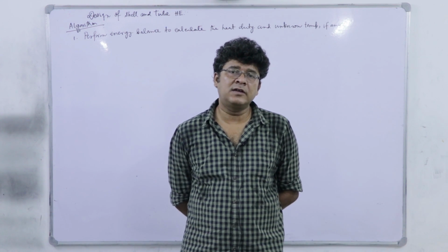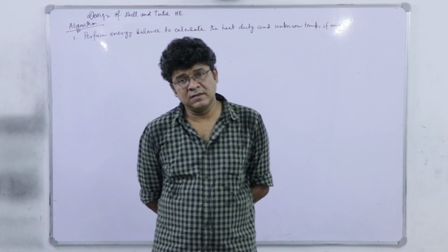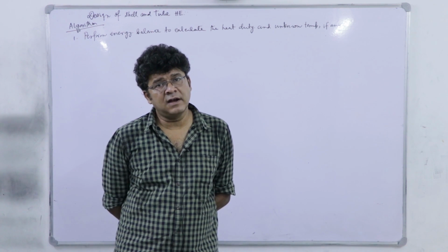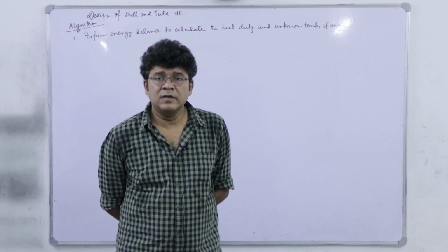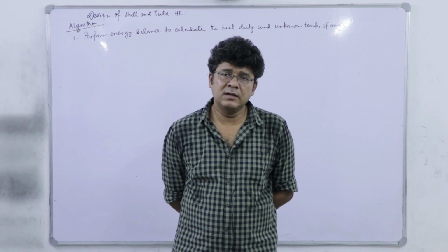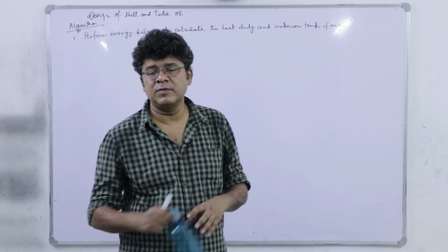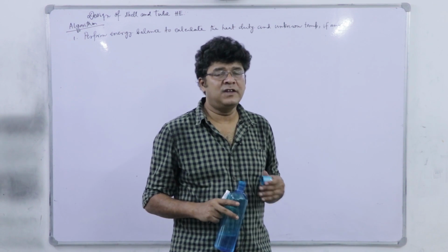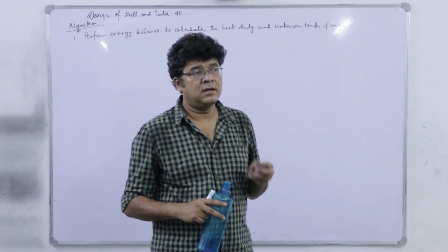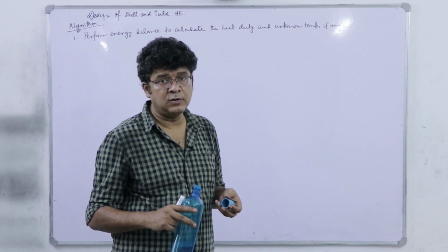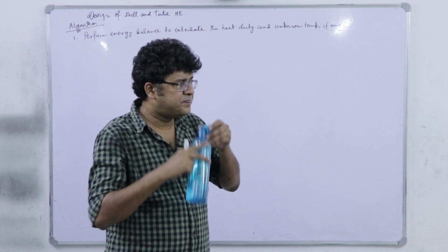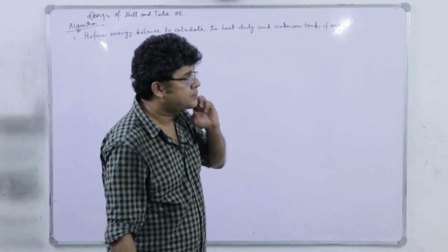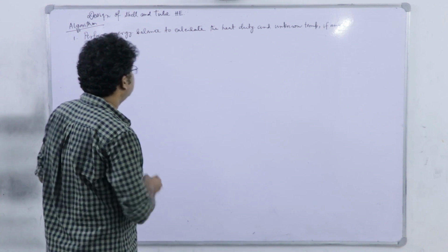So, once the inlet and outlet temperature of the cold stream, specifically utility water if I am using it, are known, we can calculate the mass flow rate. So, overall it may be an unknown temperature calculation, or it may be a mass flow rate calculation. Whatever it is, once we finish that, we can calculate the heat duty required. So, once the heat duty we have fixed, right.